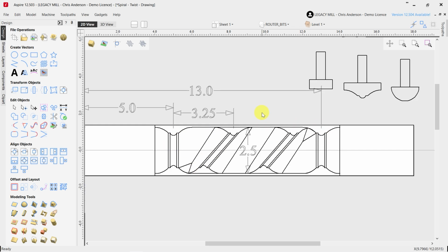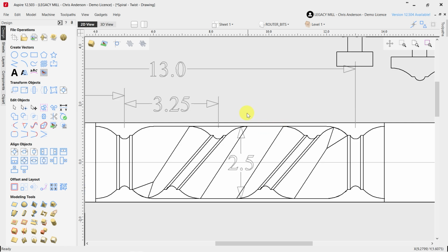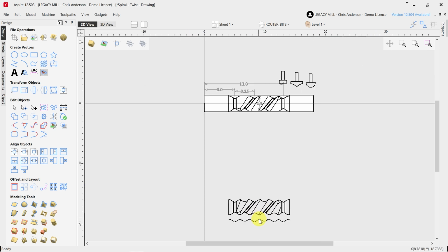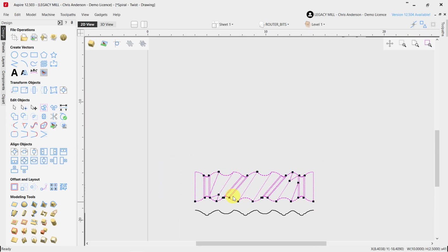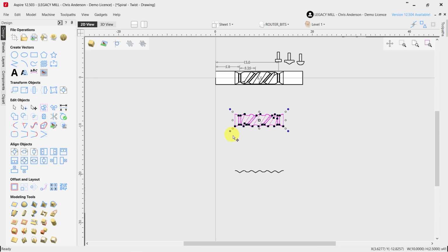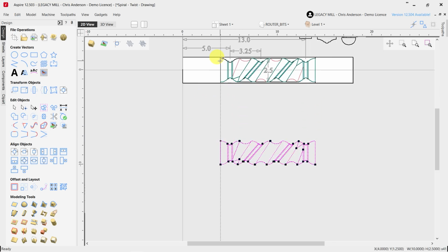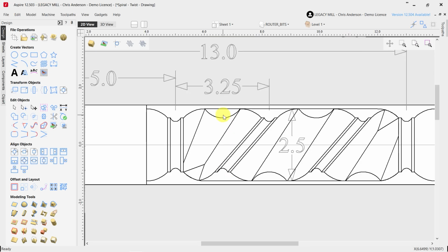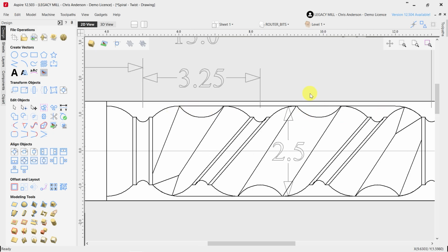And we could turn that, but I want to just show one additional thing. What if we wanted to apply a different cutter shape in the middle section here where, again, nothing is being applied yet? Okay. So for example, I have another design down here to show exactly that. So this is, again, the exact same twist, except this time what we've done is we've applied this ball cutter, a core box cutter, to follow the twist in those middle sections where the classic spiral was not cutting. And it gives us another design aspect. So let's go program that as well.